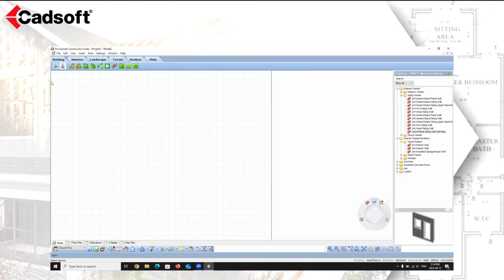And the next thing we're going to be looking at is adding in berms and trenches. Now, the berms and trenches is another tool to allow you to create, again, a running hill or a berm or a trench that's going to be down into the earth. So again, you're going to select the option. You're going to give it your value. So you're going to say how high or how far below the grade do you want your berm or your trench to be.